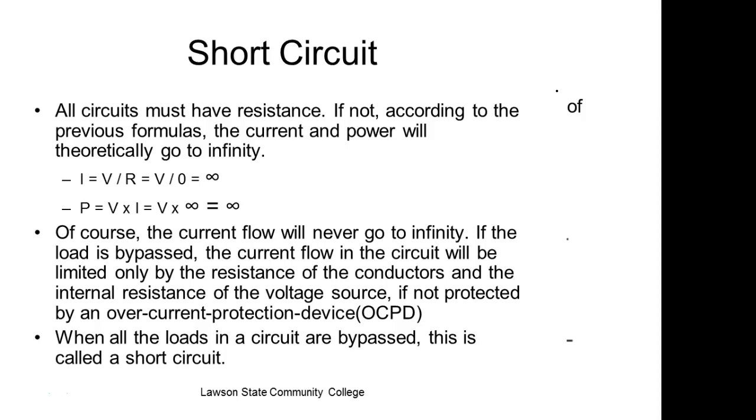Yeah, usually that indicates that you're running it close to its capacity. Technically, with circuit breakers, you're never supposed to run over 80% of their capacity. So a 15 amp breaker, you should never run it over 12.5 amps. And the closer you get to the capacity of it, the more problems you're going to have. So would it be bad to put a stronger breaker in? Yes. And why is that?